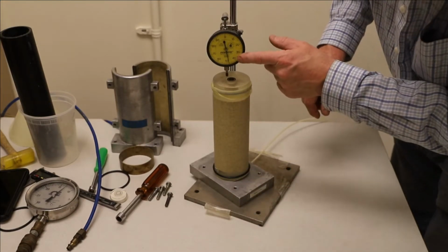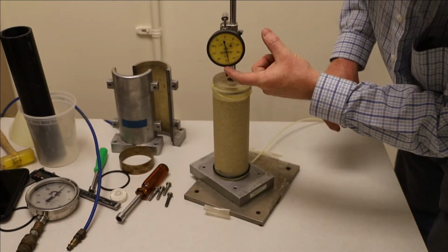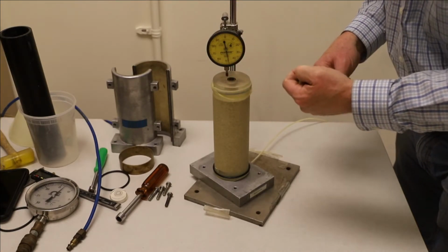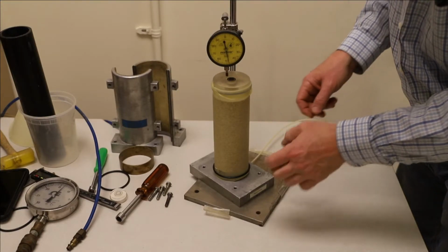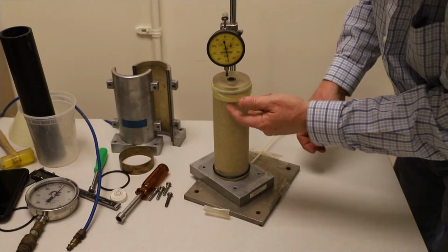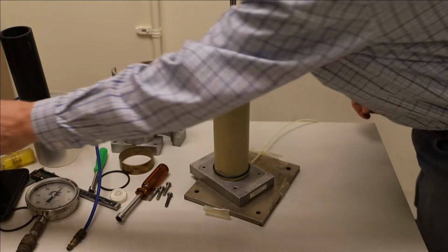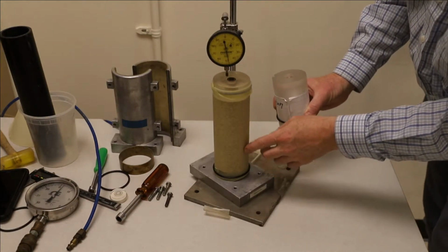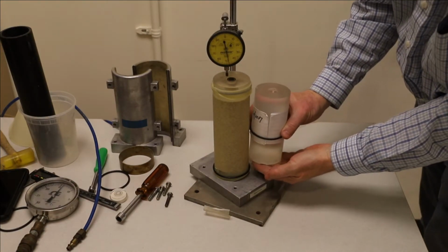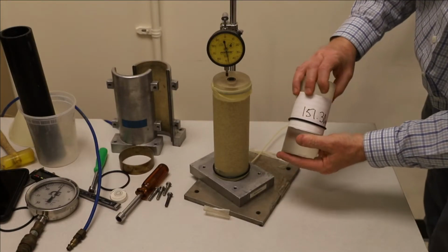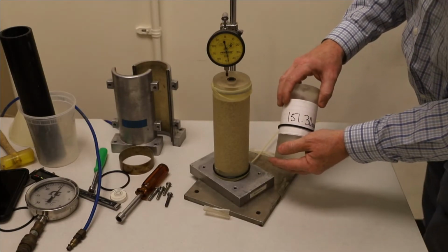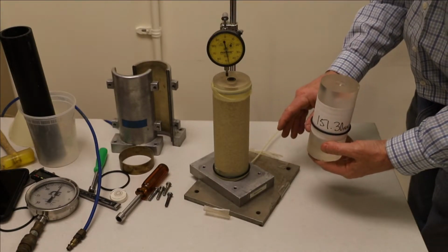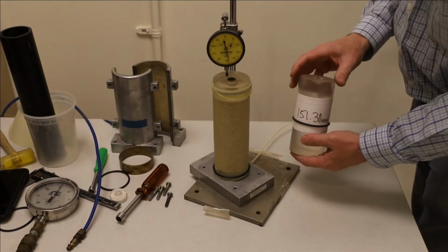So what we can do is, of course, this dial gauge is just positioned arbitrarily, right? So the reading itself doesn't tell us what the height of the specimen is. But if we take a reading with the specimen in there and compare that with a reading we took earlier where there was no sand in place. So in place of the sand, we had a standard specimen of a known precise height between the same caps in the same system with the dial gauge in the same place.